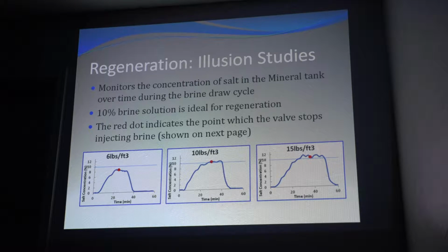You're going to get to a lot of sites: my injector failed, it's plugged, my brine tank overflowed. All right, now I've got all this water in my tank. Should I bail all this salt water out of here, or isn't it going to stay this way? Well, no, because typically you're drawing all your salt out in about 20 minutes or less.